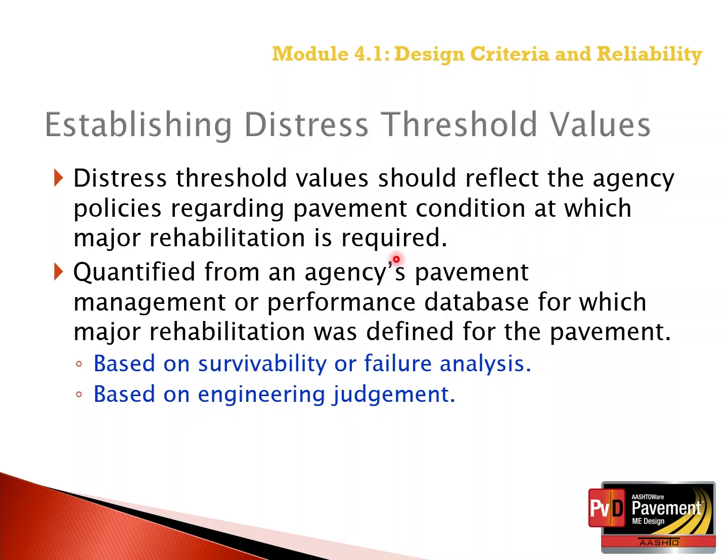It's also quantified from an agency's pavement management or performance database for which major rehabilitation was defined for the pavement. It can be based on a survivability or failure analysis. It can also be based on engineering judgment. But whether it's based on a survivability analysis or engineering judgment, it should be tied to how the agency operates, maintains, or its policies on rehabilitation of its roadway network.